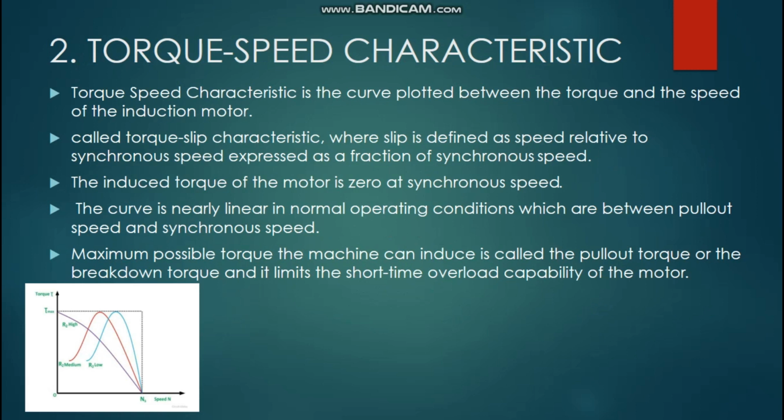The maximum torque is independent of the rotor resistance, but the exact location of the maximum torque Tmax depends on it. Greater the value of the R2, the greater the value of the slip at which maximum torque occurs. As the rotor resistance increases, the pull-out speed of the motor decreases. In this condition, the maximum torque remains constant.